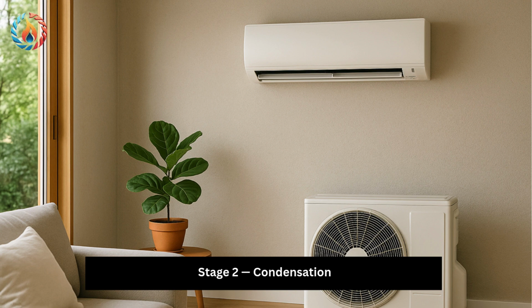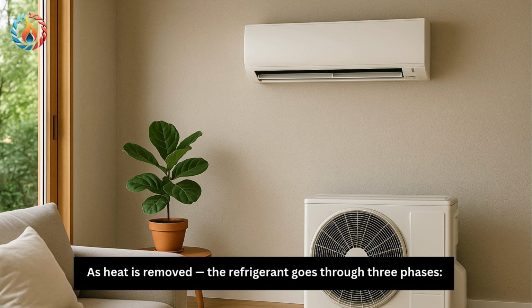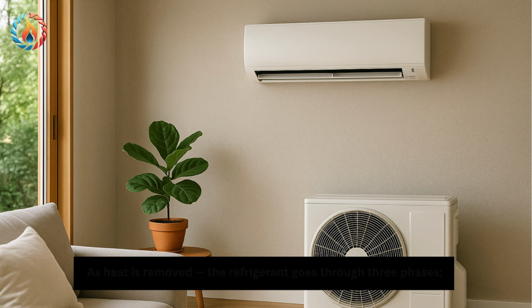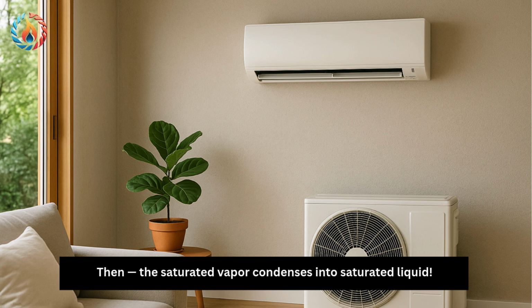Stage 2. Condensation. The hot superheated vapor enters the condenser. The condenser rejects heat to the surroundings. In an air-cooled condenser, a fan blows air over the coil. In a water-cooled condenser, water flows through the tubes. As heat is removed, the refrigerant goes through 3 phases. First, the superheated vapor cools down to saturation temperature. Then, the saturated vapor condenses into saturated liquid.